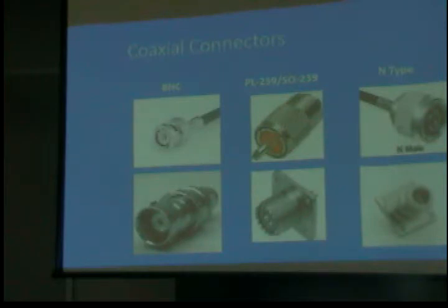There's a large one called an N connector that we will talk about here. The N connector is a better connector, but nobody uses it much until you get into commercial. And there's also another one now, and I need to get the picture on here. It's called an SMA. It's the little one that is used on the Baofengs and most of the newer transmitters.